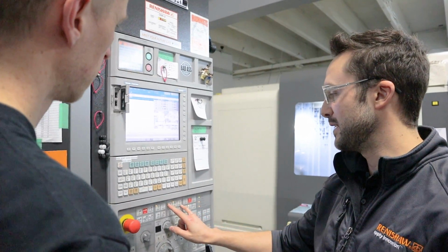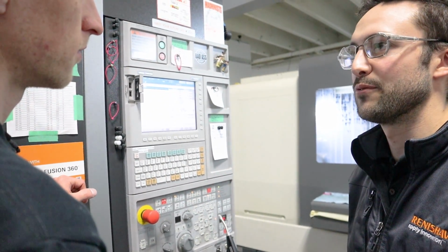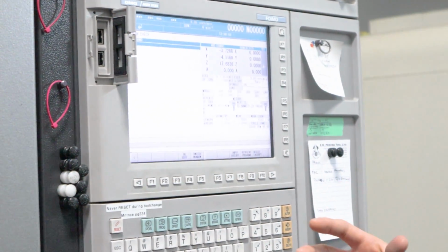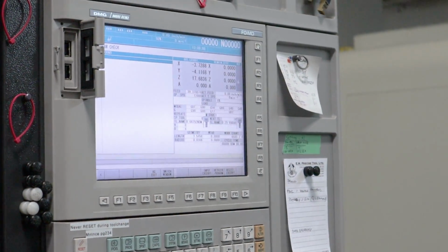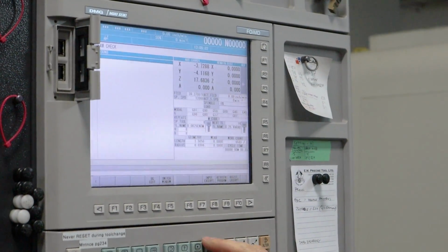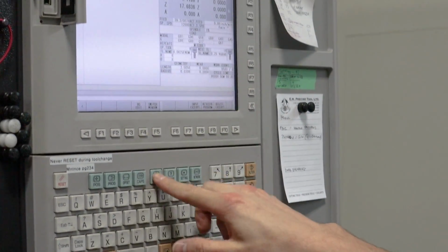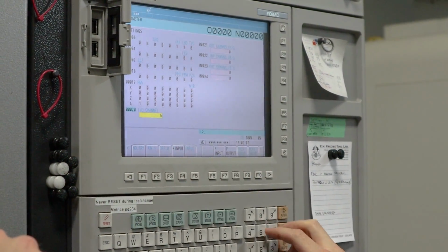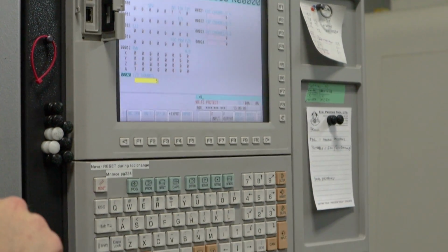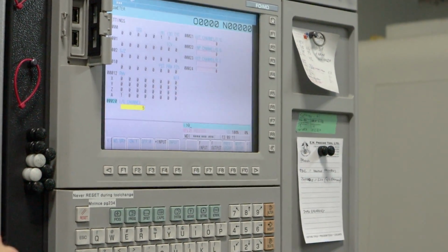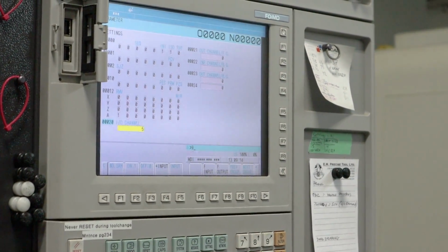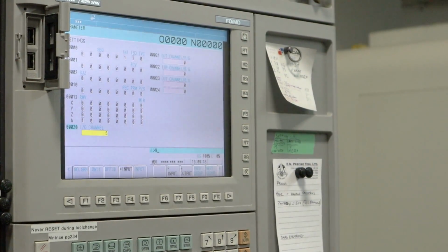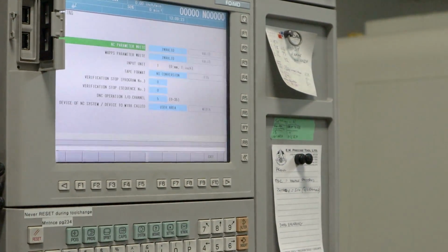So for DNC, you would be channel 15. For the port that we're using on the Fanuc controller, which is the embedded one in the back of the standard I/O port, this is what I think I need to change here. Should be 5, but we'll do this for fun. We'll jump over to 9. Between data server and embedded, they each use a different channel, and it's always between 9 and 5. I just haven't come to memorize the settings.